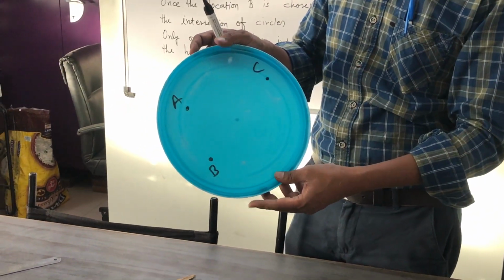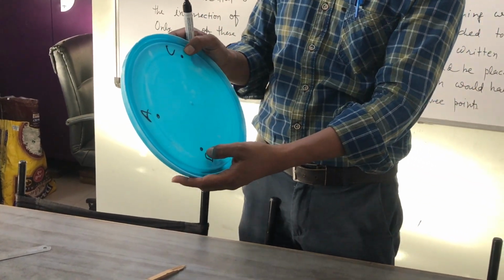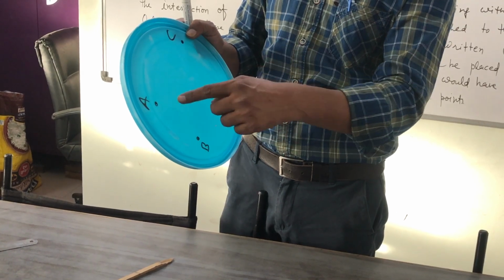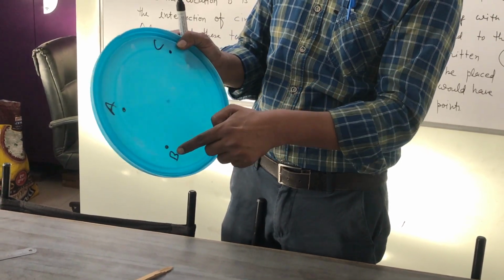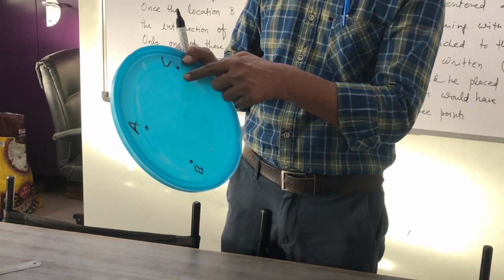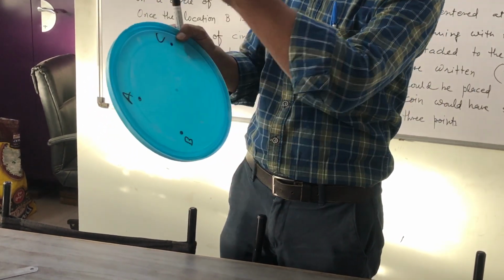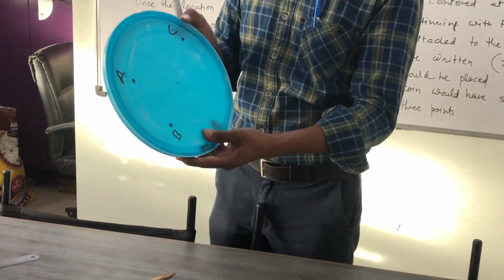After the location of B is fixed, C must lie on the intersection of two spheres, having radius DAC centered at A and radius DBC centered at B. For these two spheres, the intersection is a circle. So for this, we require one more angle.